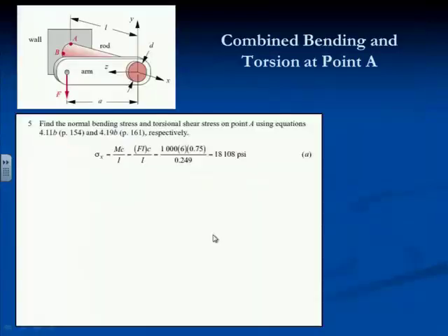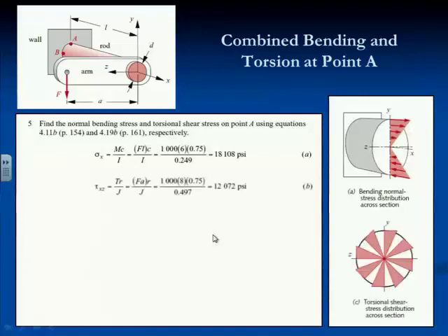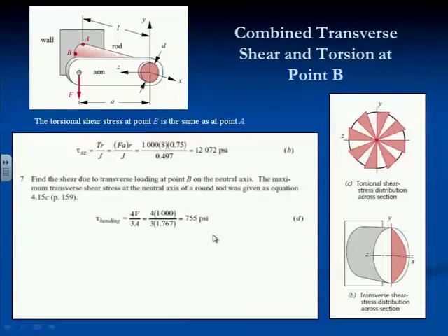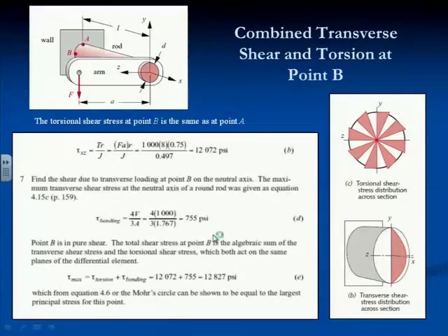So this is a case where the shear due to bending could be a problem. So we do want to take care of it. So back to where I just left off. It is still not very big compared to the other one, because I've got a long moment arm on that place where I put the F. That gives me a big torque, so that's tending to dwarf that.